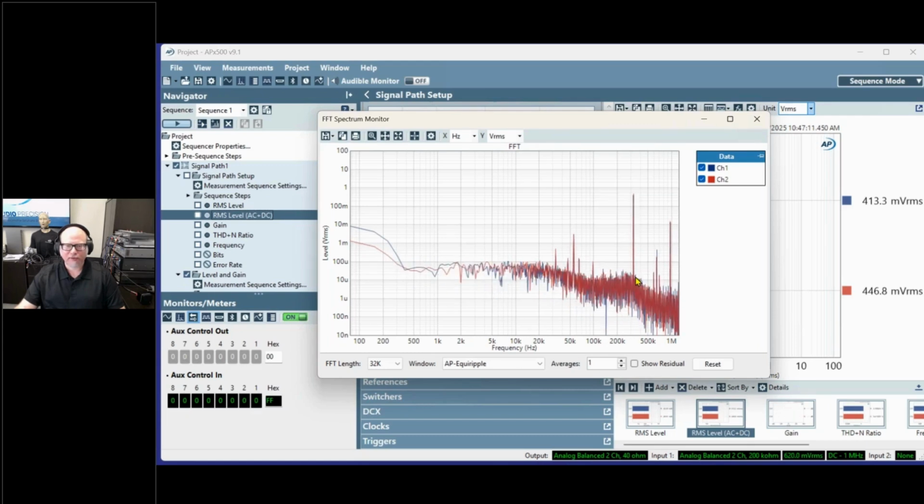But we have a bunch of stuff from the switching frequency of the amplifier, which is actually quite high in amplitude. Here at, what is that, about 300K, we've got about 500 millivolts, 400 millivolts actually, I can see it right here, from the switching fundamental. And we do make a product, or actually I should say a family of products for this specific thing, our so-called AUX switching amplifier measurement filters.